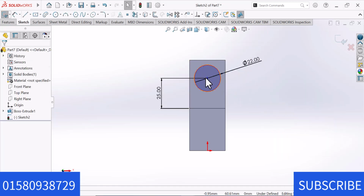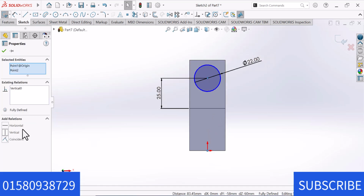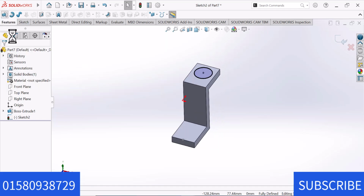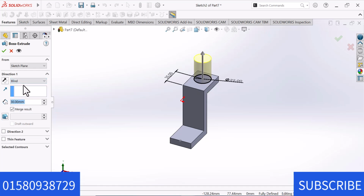Select this point, controls this point, vertical. Okay. Now go to Feature and select Extrude. Now from blind, give the value 12. Okay.